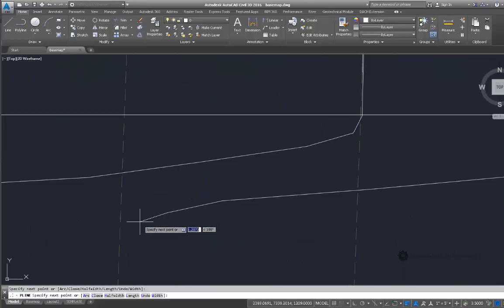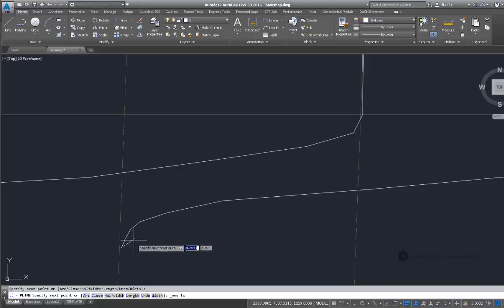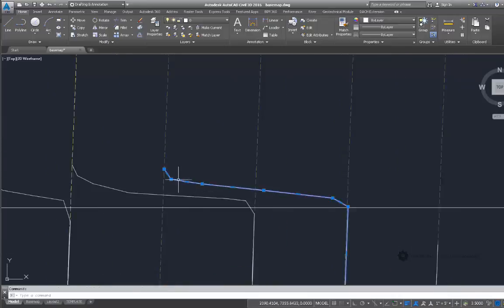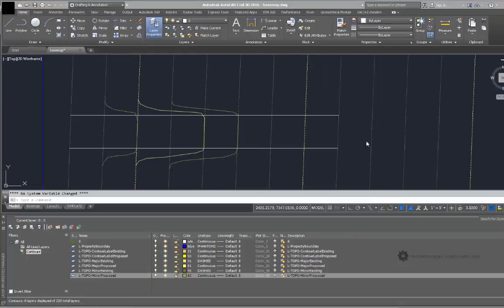And usually, towards the end here, I try to curve it so it looks like it's gradually going to meet back with the grade. If you just abruptly cut it off, the surface gets really rough. You may not see that now, but as we start to build surfaces, you'll see how there's this kind of almost like a pit in the surface. And we'll study that as we start doing a little bit more grading. So I can add a vertex if I wanted to.